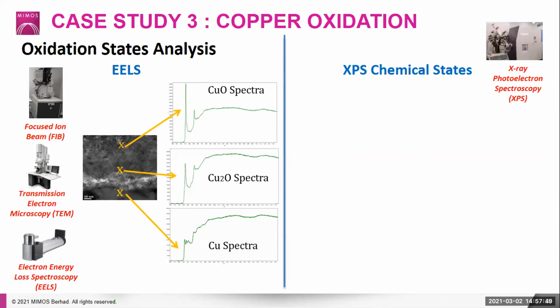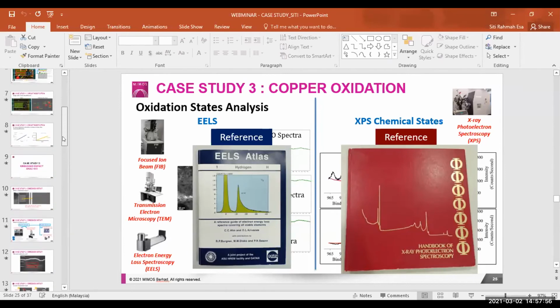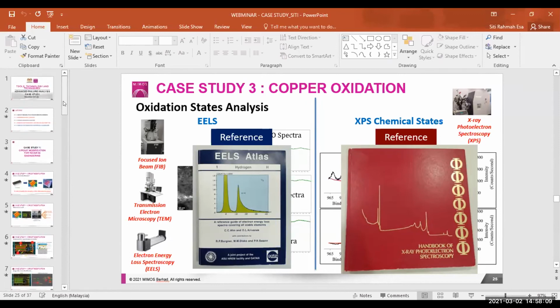Okay, related to FIB, which is expected, there are a lot of questions on FIB. Probably you can share the accepted sample dimension for FIB cutting, and also how deep FIB can perform the cutting. For our instrument, we can accept a sample with a diameter of 150 millimeters, and the height must be less than 1 centimeter. If the height is higher than that, then you have to thin it down first.